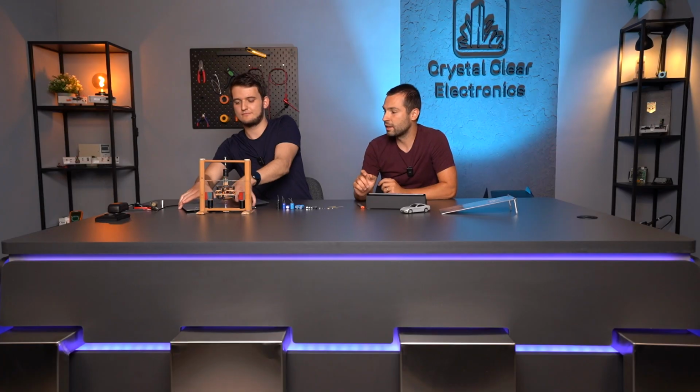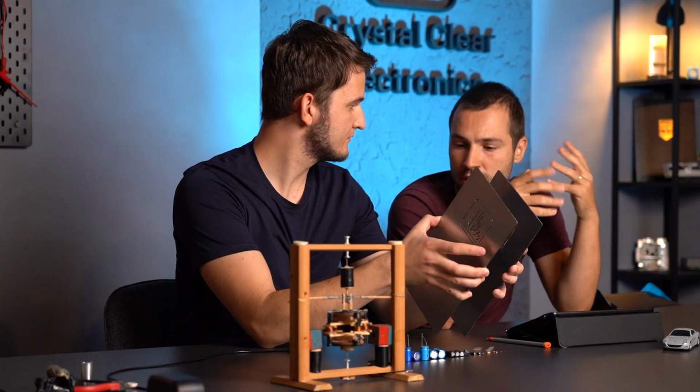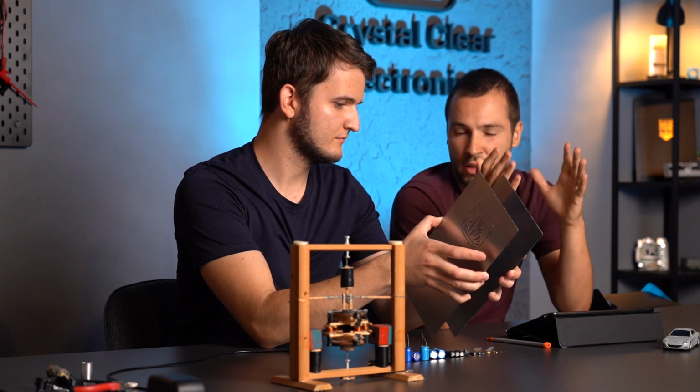The simplest is the so-called plate capacitor, which has a double-sided metal plate and insulating material, for example air, between them. The quality of the insulating material, the distance and the size of the metal plates are affecting the capacity of the capacitors, which is one of the most important qualities because it shows us how much charge we can store in the capacitor.